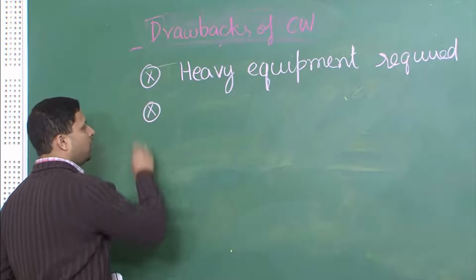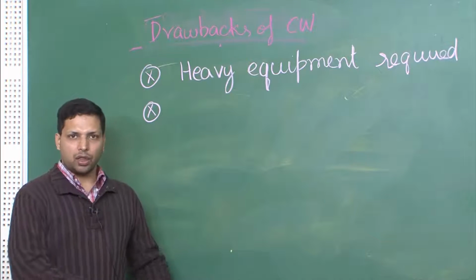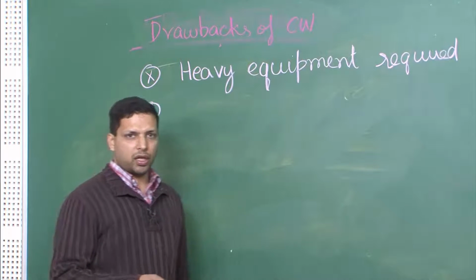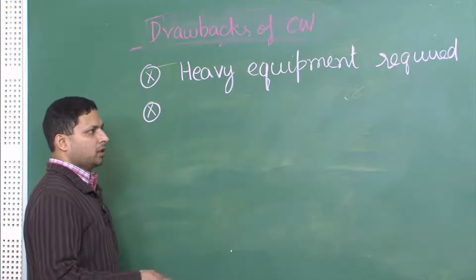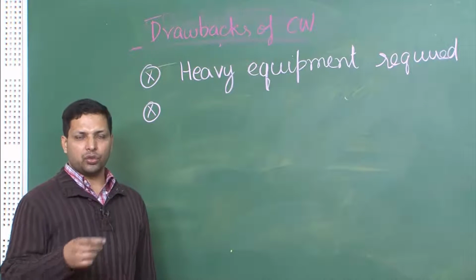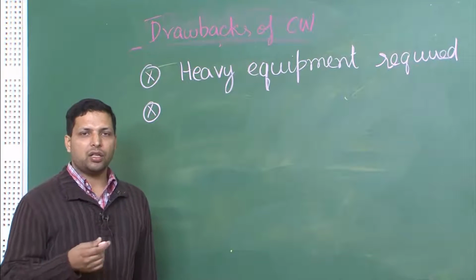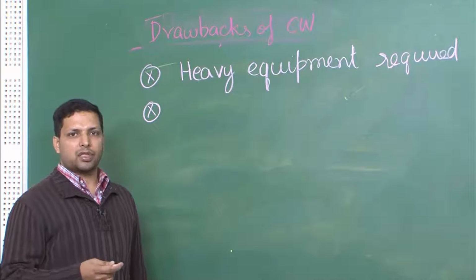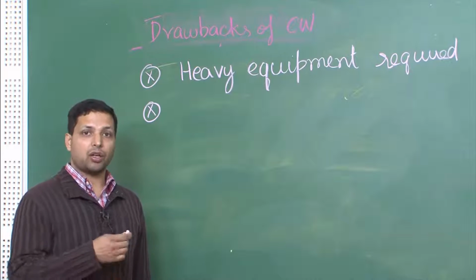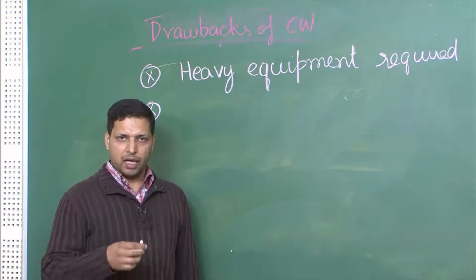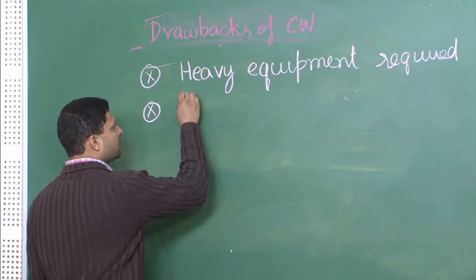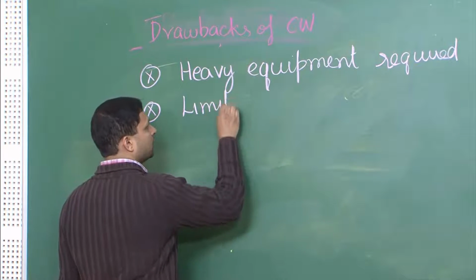Another thing is that, of course, all the properties have to be related to the microstructure. Since the microstructure is not getting recrystallized, it is getting more and more deformed, it is getting more and more defects, and very soon it reaches a point that you cannot deform it further, or it will start to create cracks, or the component will have defects at the component level, not at the microstructure level. At the component level, you may start getting defects, and that means it has limited ductility.